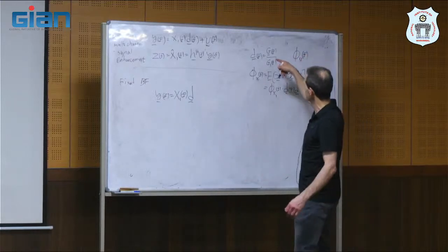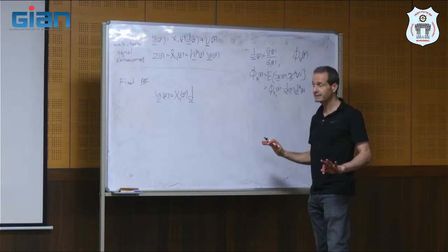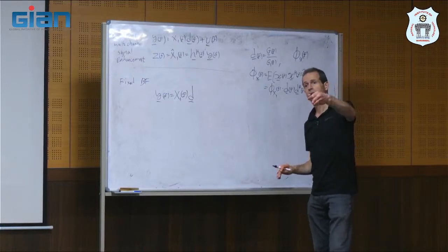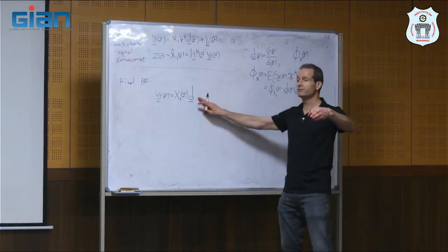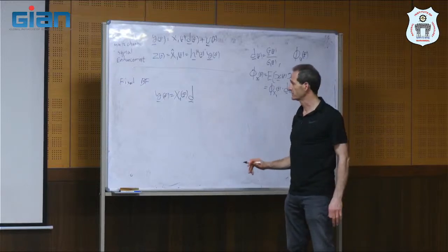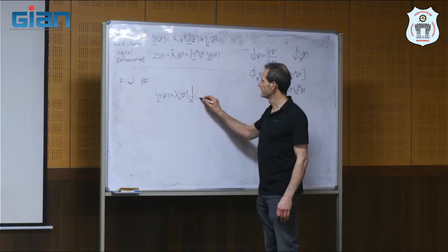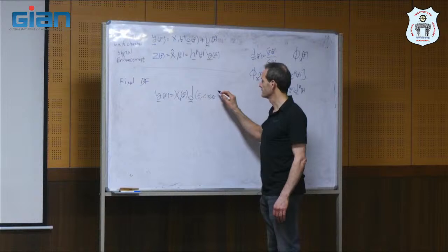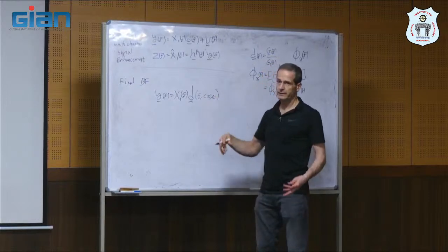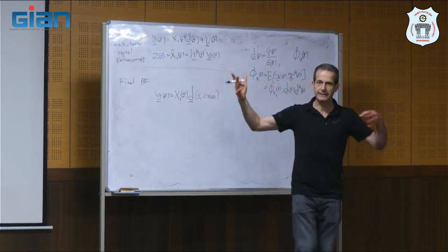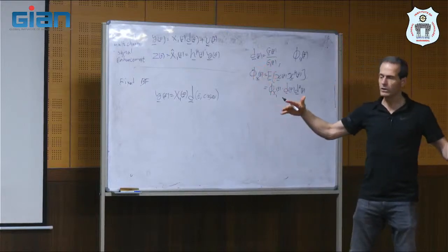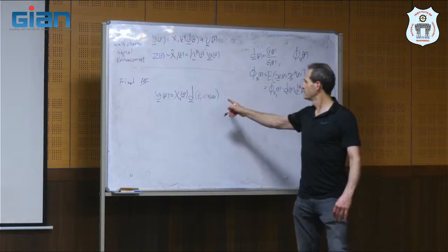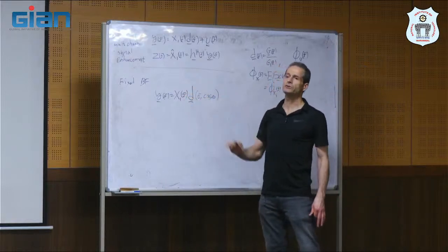All that is included there, so I don't use this. I use a simple far-field propagation steering vector without any reflection. I will call it f cosine theta. In three dimensions it depends on theta and phi, the direction. So I only know the direction of the desired source. That's it.